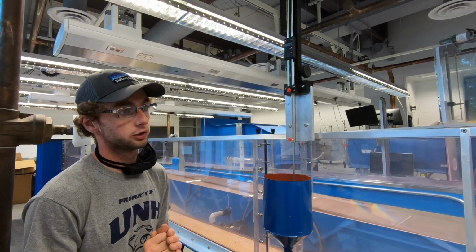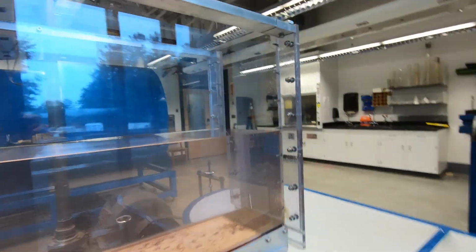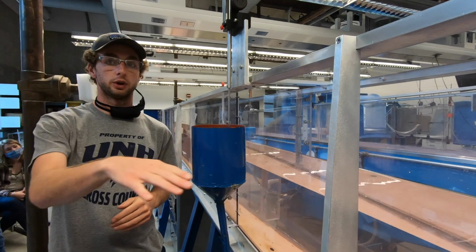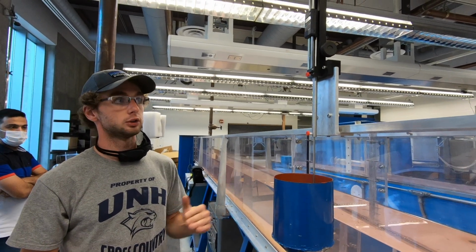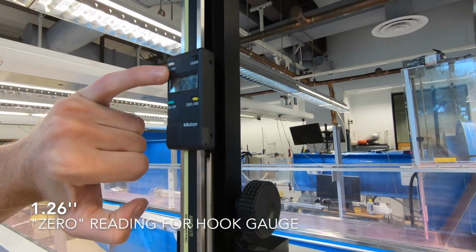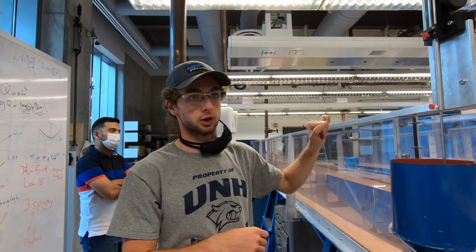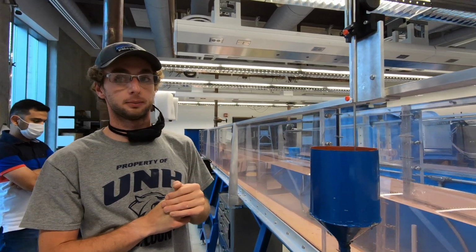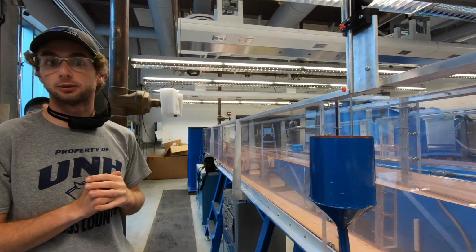We're now going to take our zero reading on the hook gauge. As you can see here, the water has ceased to flow through the flume and is now simply sitting level with the top of the weir. So this gives us the height of the weir on the hook gauge. It is currently reading 1.26 inches. You're going to take that number and subtract it from all of your hook gauge readings on trials 1 through 7 to get the height of the water relative to the weir. So that's it for part 1, and now we can move on to part 2.